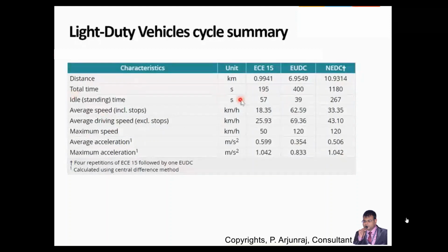Okay, let us see the comparison here. The value is much higher with respect to all these characteristics for the New European driving cycle. Even with respect to distance, total time, average speed, maximum speed, acceleration with respect to average or maximum, you can see the value is high for the New European driving cycle for light duty vehicle application. So most of the European countries, all the European countries, follow this NEDC cycle.